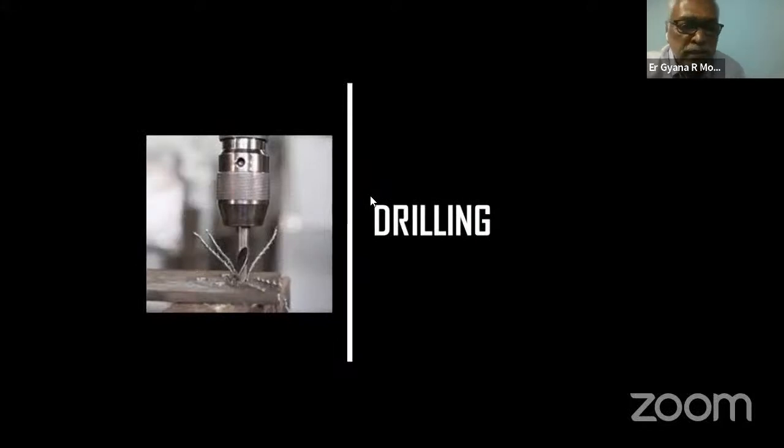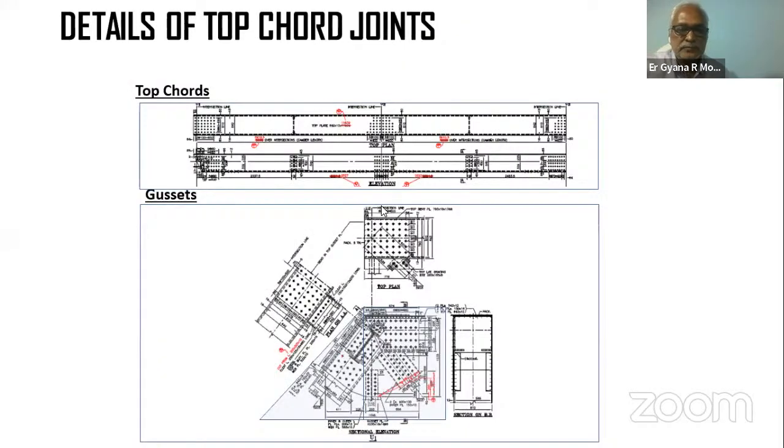Then coming to drilling, as we had discussed earlier, when you are making a girder, drilling is a very vital thing. Unless the drilling is properly done and the orientation of the hole is properly done, there will be a tremendous problem at the assembly of the girder, and most likely we may not achieve the camber that is required if there is an error in drilling.